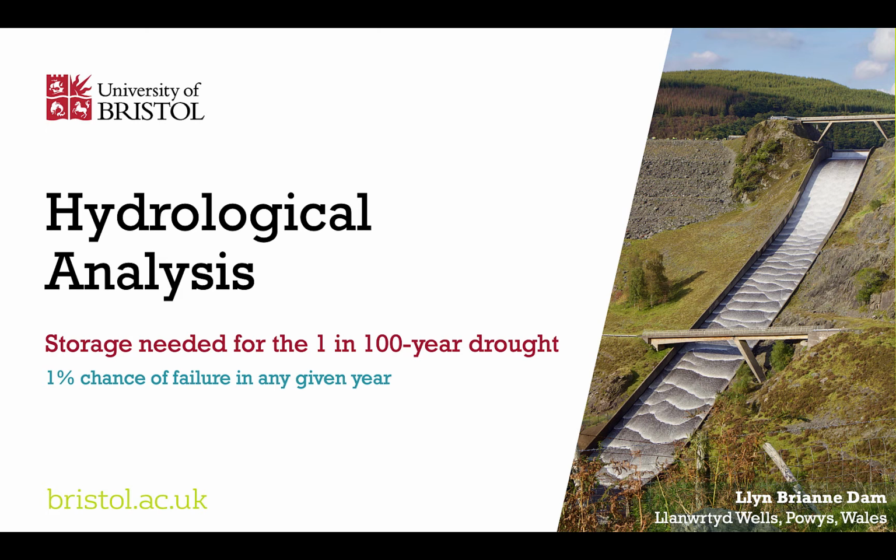Once you have identified a suitable location where the catchment water yield is greater than the demand that's required for the new town and to maintain the compensation flows in the river, the next thing you need to do is to work out how much storage is going to be needed in order for a reservoir that's constructed in this location to have only a 1% chance of failure in any given year. Another way of saying this is that this is the storage needed to withstand the 1 in 100 year drought scenario.